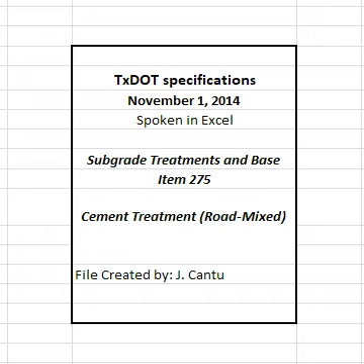Before final acceptance, the engineer will select the locations of tests in each unit and measure the treated depth in accordance with Tex-140-E. Correct areas deficient by more than 1/2 inch in thickness or more than 1/2% in target cement content by adding cement as required, reshaping, recompacting, and refinishing at the contractor's expense. Remove or rework areas that lose required stability, compaction, or finish, as directed. When a section is reworked more than 4 hours after completion of compaction, add additional cement as directed. Provide additional work and material at no additional cost to the department.